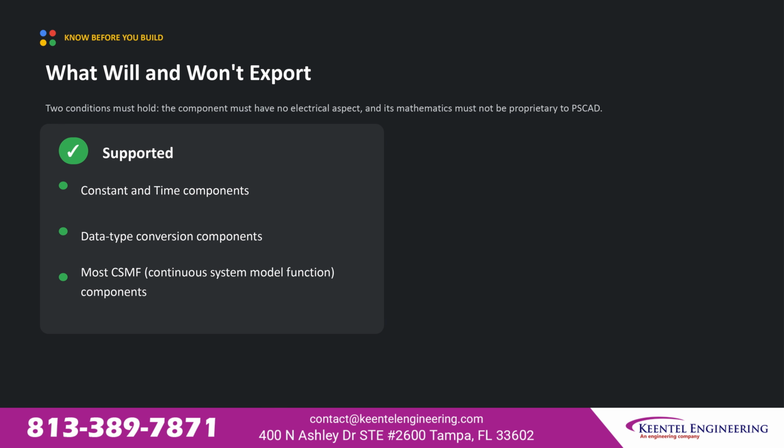Not every PSCAD component can be translated by the C-code generator. 2 conditions must both be satisfied. The component must have no electrical aspect, and its mathematics must not be proprietary to PSCAD. Components that are supported include constant and time components, data type conversion components, and most CSMF, continuous system model function, components. These cover the vast majority of control logic built in PSCAD.